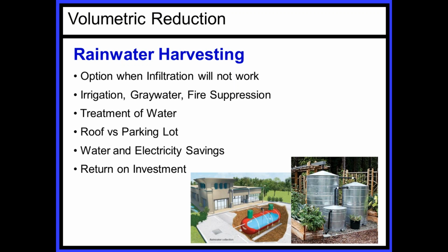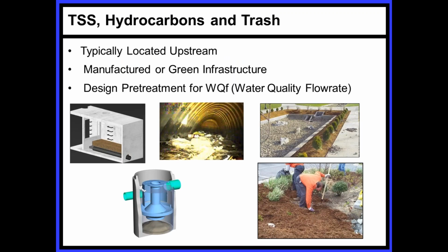The challenge that this particular sector of the LEED movement has had is the ROI. Like I showed in 2015 summer, you had way too much water for the plants, and so the plants don't need to be watered. But then when they needed water in September, those tanks are empty, so you're using potable water anyway. So trying to figure out how to size them and how to manage that flow is very difficult. The third piece that we need to talk about is treatment.